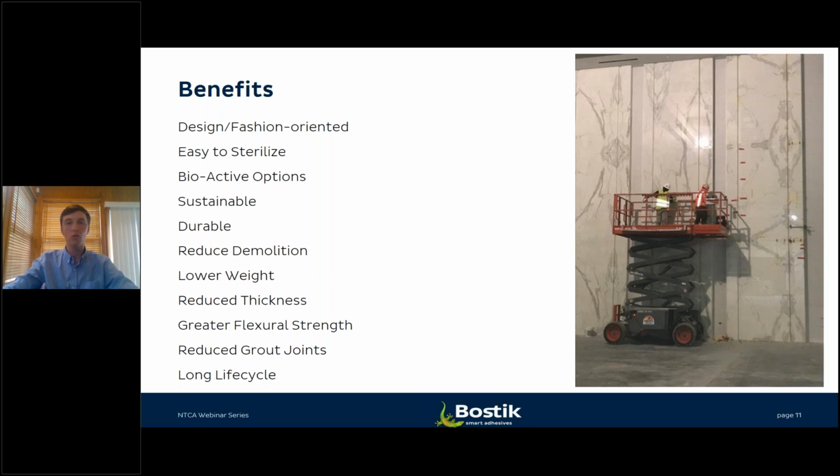And I'm sure there's a variety of others as well that have a variety of different products, whether it's TiO2 or titanium dioxide or silver that's put into the manufacturing process that allows for a photocatalytic reaction to happen at the tile's surface, which therefore can have some light self-cleaning type applications or some air cleaning type applications, which make it attractive for some areas in hospitals, attractive in facade applications, countertop spaces, shower applications.